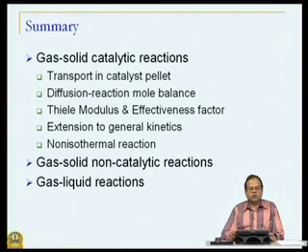So, we have two steps which involve external mass transfer, that is bulk to the surface, two steps which involve internal mass transfer, namely transport within the catalyst pellet, and three steps which typically characterize the chemical reaction taking place by interaction of our reactants and products with the active surface.